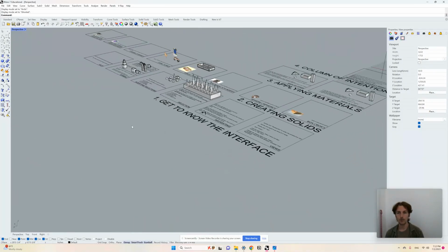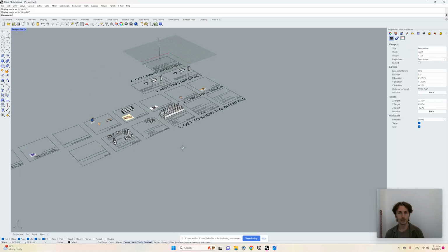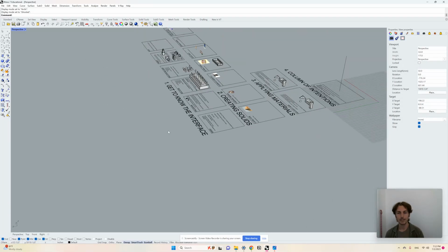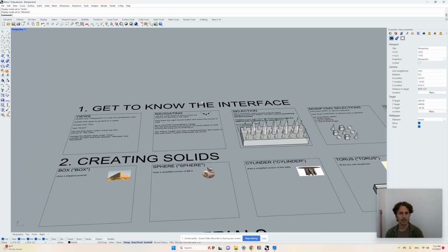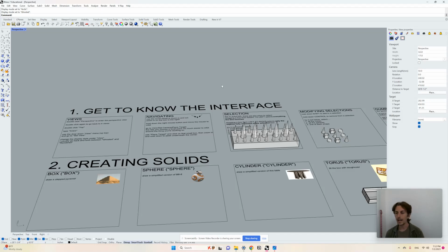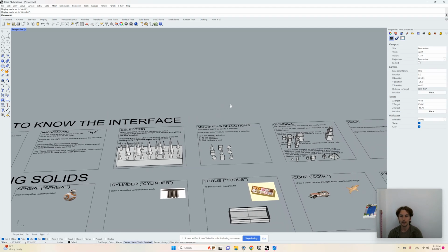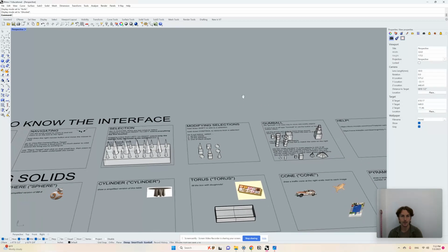So orbit away, fly around your model a little bit. Between orbit and zoom, this is pretty much everything you need to get around. Pan, I don't pan, just because I find it easier to zoom in and out, but you can hold down shift and use the right mouse button to pan. So shift, right click, and that's how you pan.